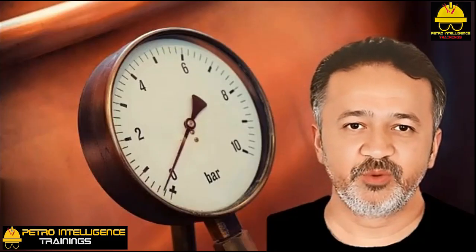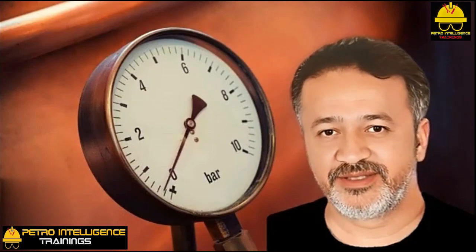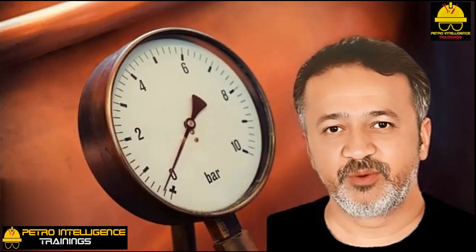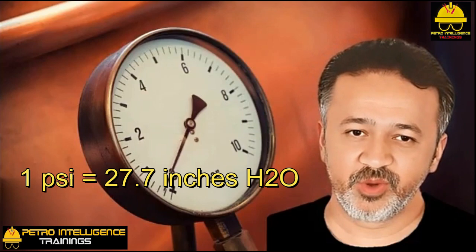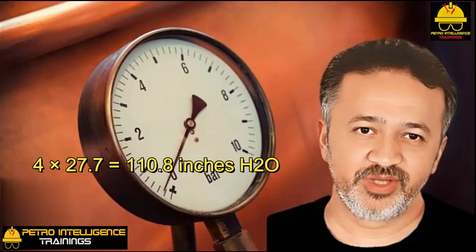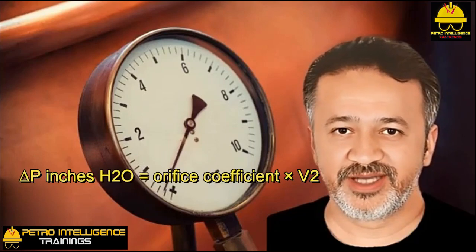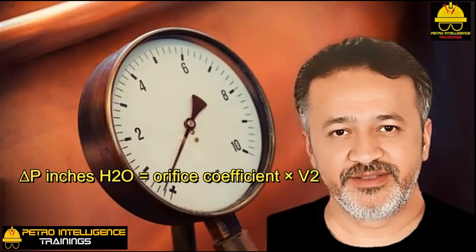Suppose the flowing fluid is water. Assume the area of the orifice is 0.1 square feet. The observed delta P equals 4 psi. Converting psi to inches of water, 1 psi equals 27.7 inches H2O. Therefore, the observed delta P expressed as inches H2O is 4 times 27.7, equal to 110.8 inches H2O. The linear flow rate, V, in feet per second is found from delta P in inches H2O equals orifice coefficient times V squared.